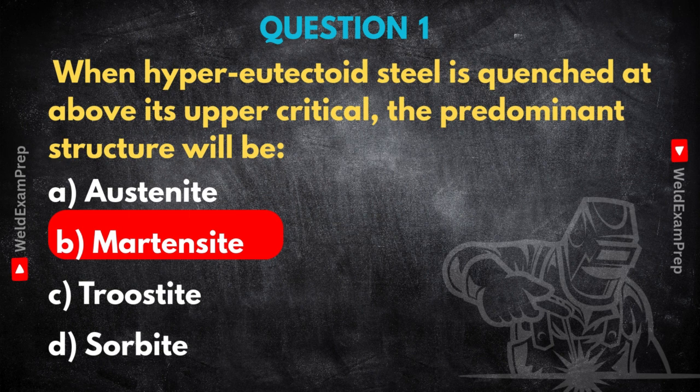So if you see martensite forming or the potential for it, that's a big red flag for potential cracking. This knowledge helps you understand why procedures might call for preheating or controlled cooling rates or maybe post-weld heat treatment. It's all about managing that microstructure. You might need to check heat treatment charts, maybe do hardness tests, or look closely for cracks with NDT. It's about preventing failure by controlling the structure. That's really clear. So the brittleness is the key takeaway for weld integrity.